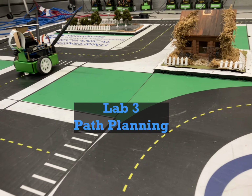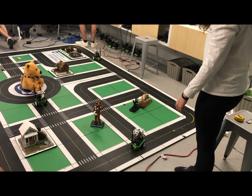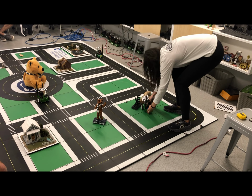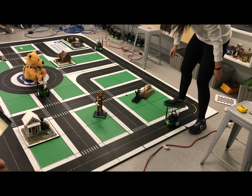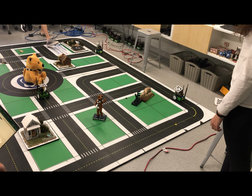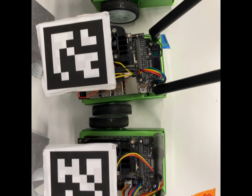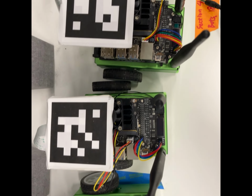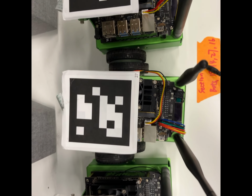The third laboratory session focused on path planning. In order to plan a path, our robot needs to know its current location on the map and its destination. To access the live location of the robot, we used an April tag system. April tags are similar to QR codes, but are designed to encode far less information, only 4 to 12 bits.